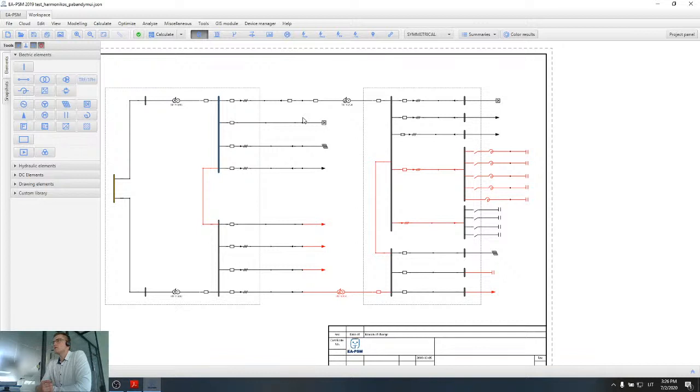And these load flow calculations are used for 50 Hz and higher frequency calculations as well. These calculations are based on international standards like IEC as well as IEEE. So calculations can be checked based on these standards, and on our site you can also find validation cases where we compare the results of our software with example results from the standards.